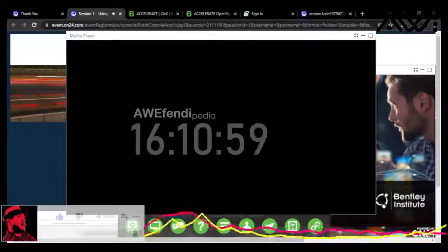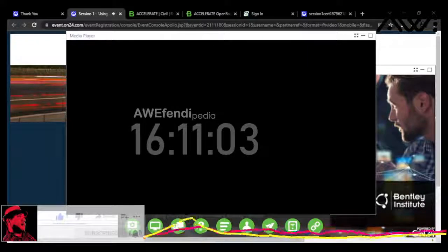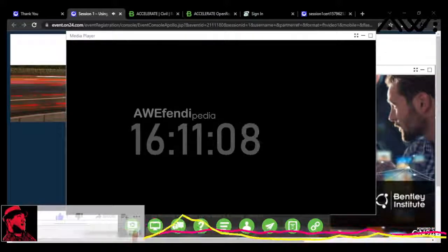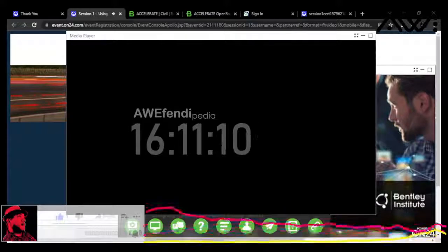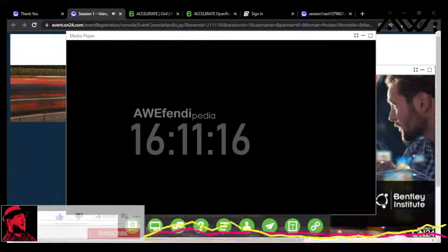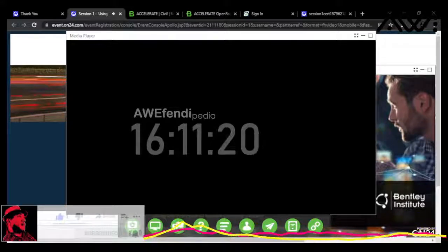And while I have this cleaned up a little bit, let's go and check the location of our survey there. I'm going to hit the drop down for view attributes, which is up here in the top left in your window. And I'm just going to turn on the Bing background map here just to check the location of our survey. You remember when I first created the seed file, I assigned the geographic coordinate system. I just want to look, are we lining up pretty good geographically?